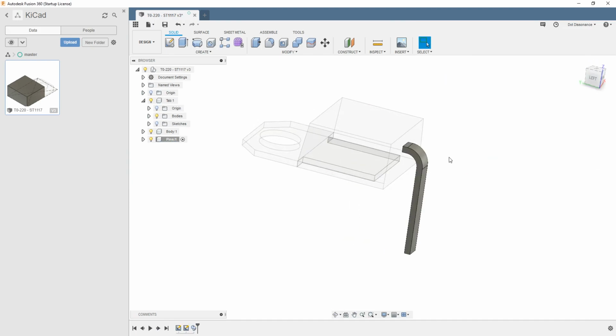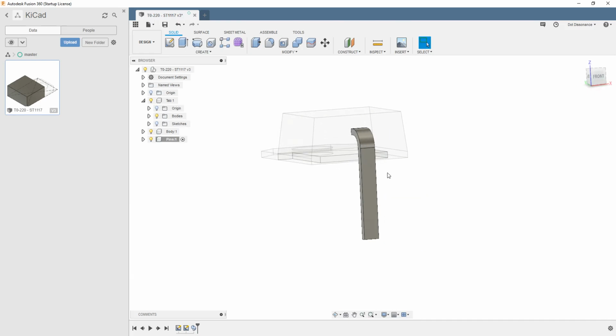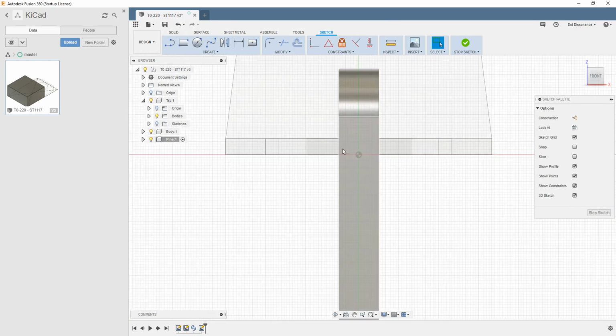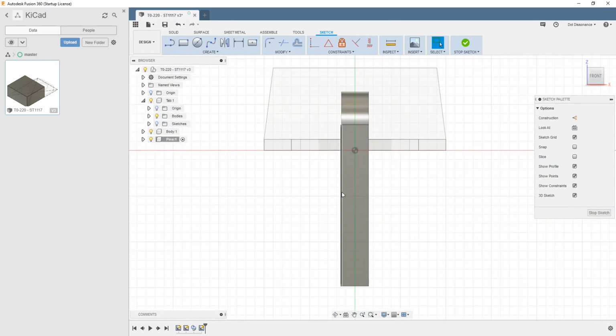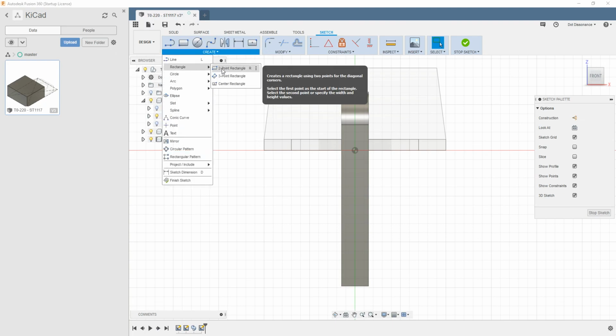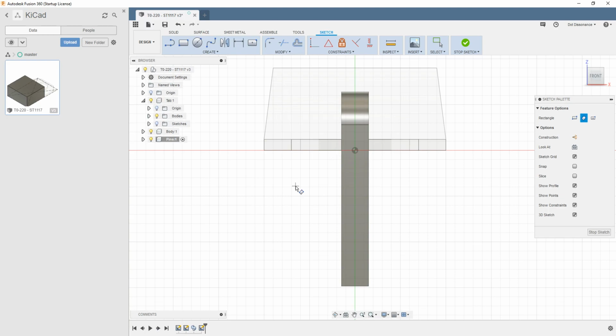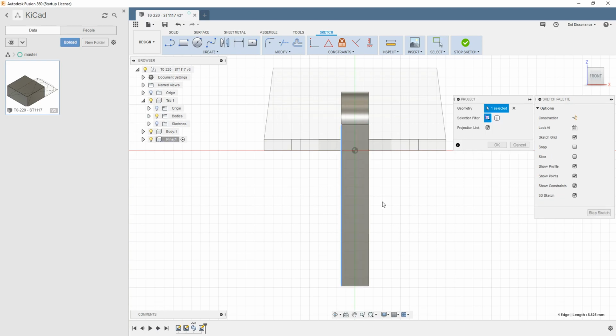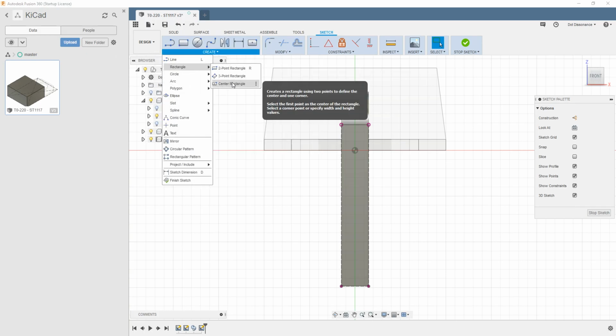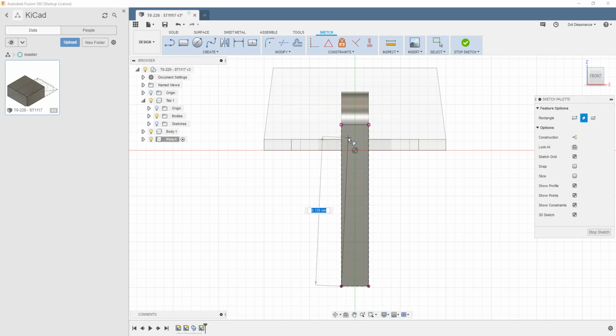Then the rest of it, I figure this bend radius is kind of where that fatness would be. And so we'll come here onto this face here. And how about this? We'll just grab, yeah, we'll just do it like this. We'll grab a rectangle. And how about we do a projection first? Yeah. So we'll grab this. We'll go here, we'll go there, we'll project, enter, should have made it a construction element. Good. And now our rectangle, we'll go from here, doesn't really matter, something like this.